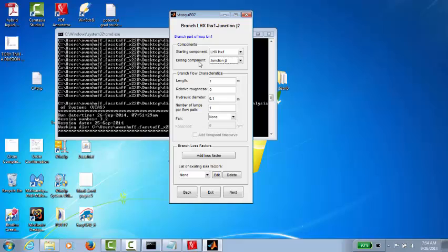Another subtle difference between the liquid heat exchange system and the hybrid air liquid heat exchange system is you notice here there's no dash between the LHX and the 1. The reason why is because unlike the rear door heat exchange system, where we only specify the type of rear door heat exchanger, and you can then have individually placed rear door heat exchangers in each row, here the liquid heat exchange system applies for all the rows that you want to connect to it. So this LHX that we define here is similar to a CRA or a cooling tower in the sense that you define the actual piece of equipment, not the type of equipment. And since this is downstream of the LHX, we have to provide our CDU pump.